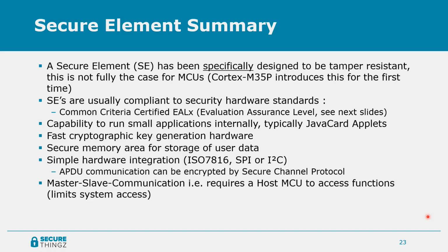The secure element has the capability to run small applications internally, typically Java Card applets. It has very fast cryptographic key generation hardware, which is very important. It can actually generate keys very quickly. It oftentimes has secure memory areas for storage of user data. It has simple hardware integration, and it has master-slave communication. So it does require a host MCU to access the functions.